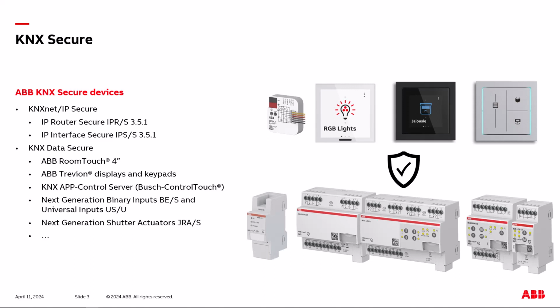We have KNX Data Secure, what we are talking about today, but we have also KNX Net IP Secure. It has to do with secured communication on the IP level. Remember, we have also KNX IP interfaces or IP routers, and the KNX Net IP protocol is also existing. About this, we were talking already, I think, 2 years ago. It's not completely new. Data Secure is neither new, but more and more new products will come now with Data Secure, especially in the ABB range.